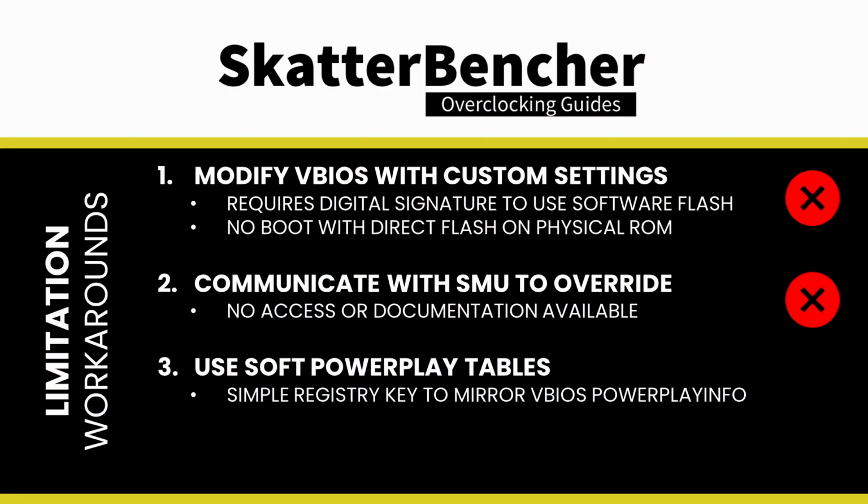The last option I want to discuss is the so-called soft PowerPlay tables. As a reminder, the soft PowerPlay table is just a Windows registry key that mirrors the information of the VBIOS PowerPlay info module, which contains the power management configuration. While AMD had said they would discontinue the use of PowerPlay from Navi onwards, soft PowerPlay tables could still work around the overclocking limitations on Navi 10 graphics cards like the Radeon RX 5700 XT.